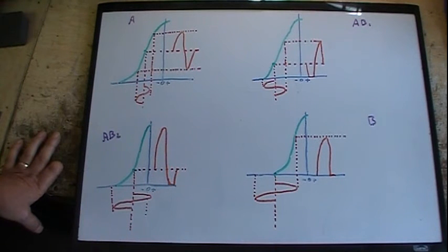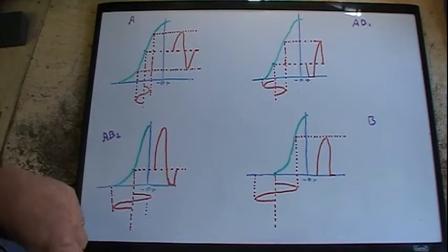Well, in the early days of radio, when they had push-pull, they actually ran Class B quite a bit. It was no big deal because transformers were cheap. Iron was cheap. So they just put an interstage audio transformer between the preamp first audio and the push-pull output tubes. You can get current out of that because it's magnetically coupled. As the transformer operates, transformer action will put current in that secondary, and if you want it, it's there.